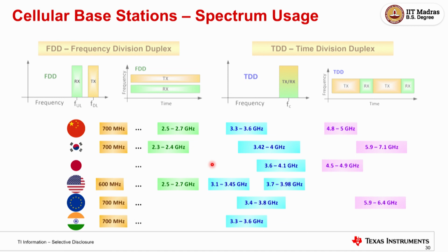Remove everything, push everything to digital, just do the bare minimum analog: take an ADC, take a DAC, sample the signal and give it to digital. Everything is done in digital. But the challenge in that is you need to have technologies to build those high speed ADC converters or DAC converters. That's where the challenge comes.